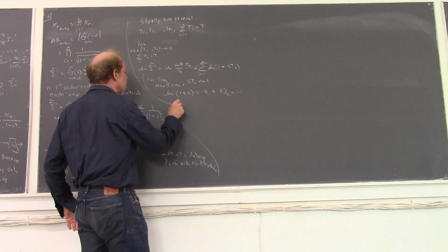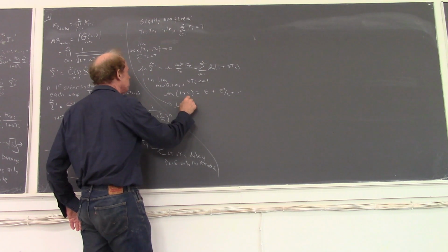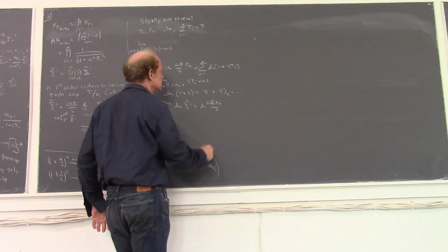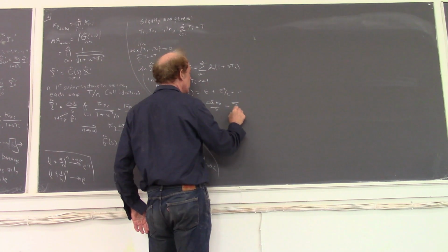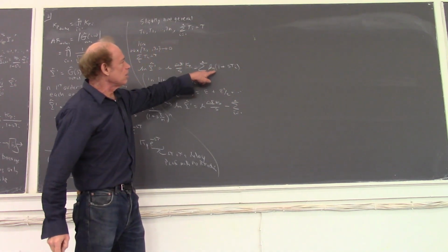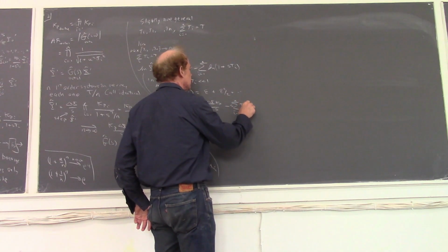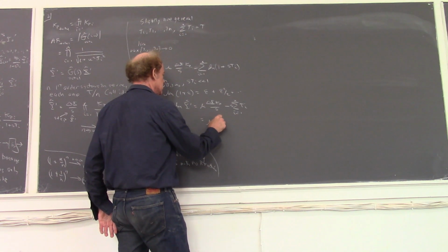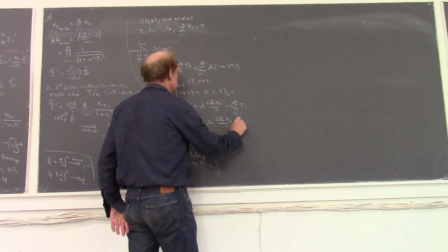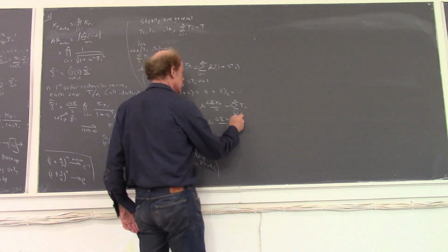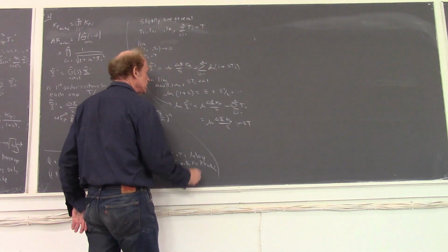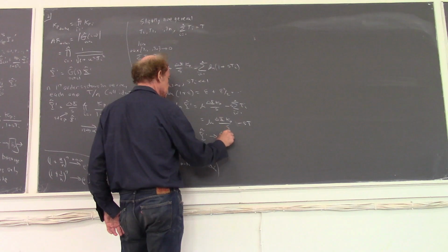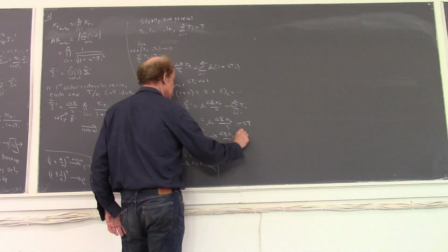So if I just keep the first term, the log of y prime tilde is the log of delta x kp over s minus the sum, i equals 1 to n. Instead of the log of 1 plus s t_i, I have the sum of the s t_i's. Well, the sum of the t_i's is just equal to T, in which case y prime tilde goes to, in this limit, delta x kp over s e to the minus sT.